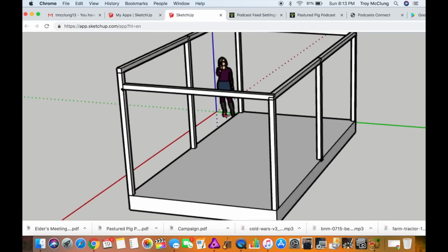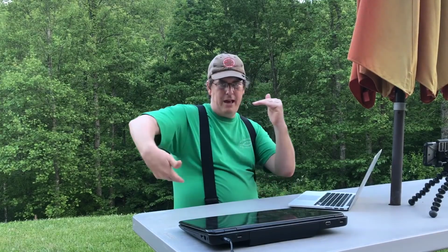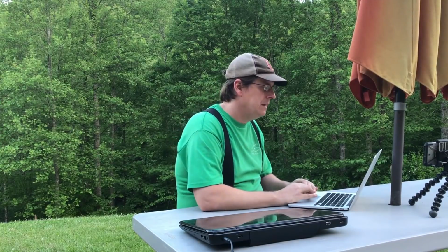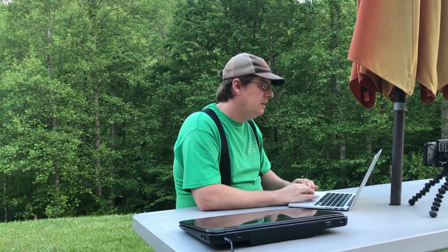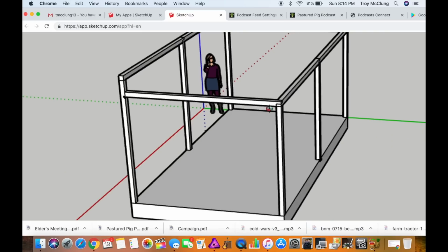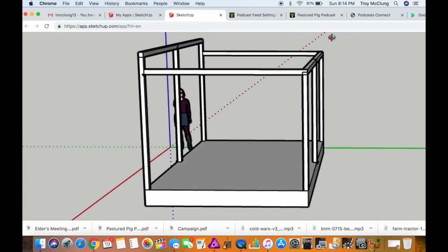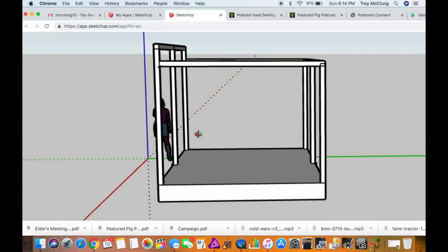The same thing here. We're going to do half lap joints, and those joints are going to half lap at, of course, a 90-degree angle. And then, of course, we'll drive pins down through the top. We'll do dowel rods. When it comes to having these side horizontals tying in the front and the back, technically where the lady is standing is the front of the deck, or the ground side. The hillside falls away behind it, so our roof angle will go with the slope of the land.